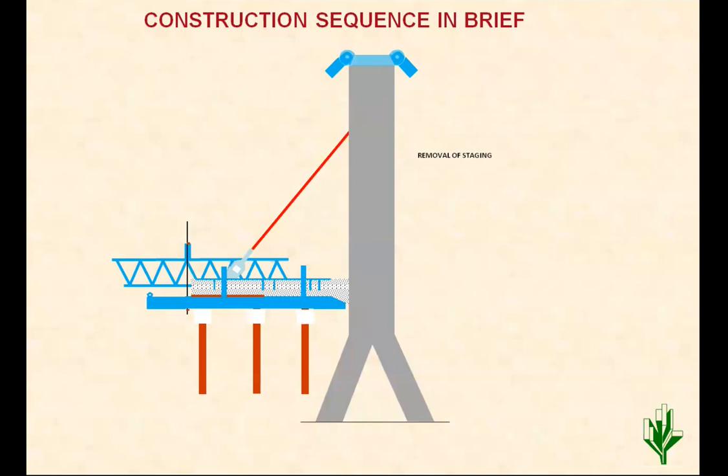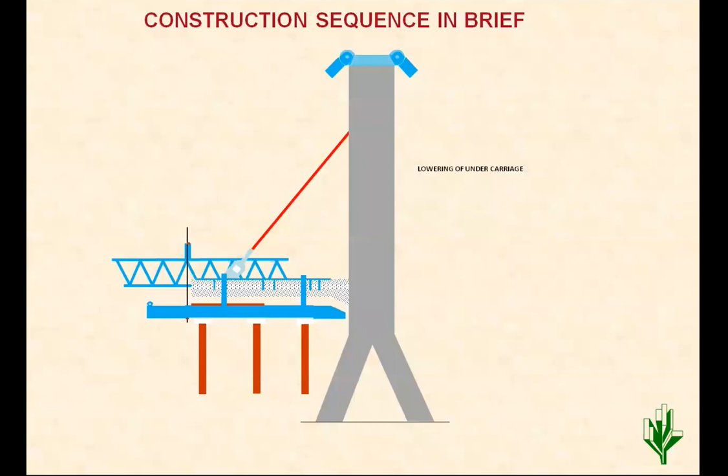Now after the first cable is traced, the deck is supported on a cable, and that is not requiring any support from below. The shuttering beam or staging beam, whatever is there, is hung from the beam with two hangers and one more front hanger which is supported on the truss on the top of the deck. Now it can be lowered, so some gap is created between the beam, and it is possible to move further.